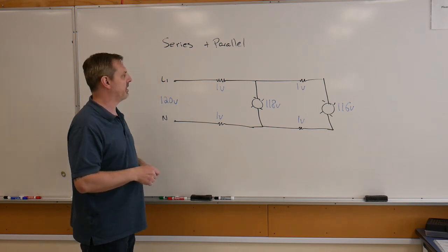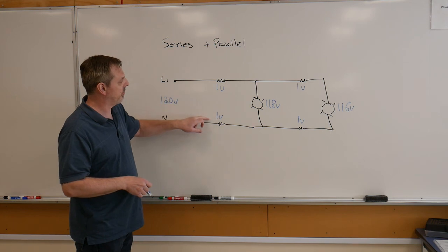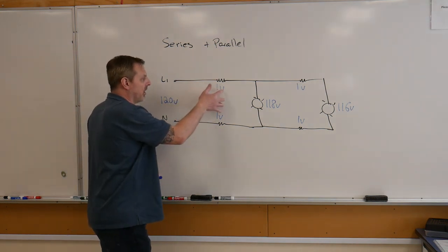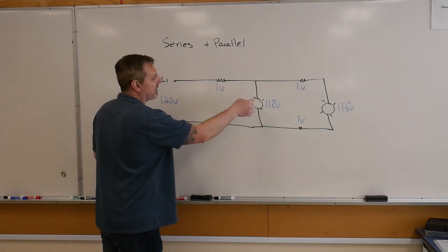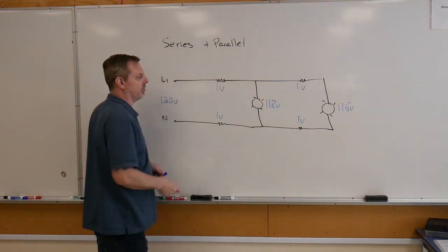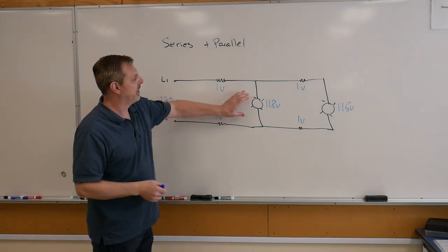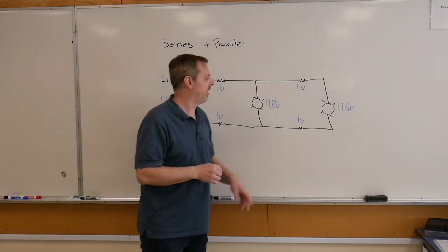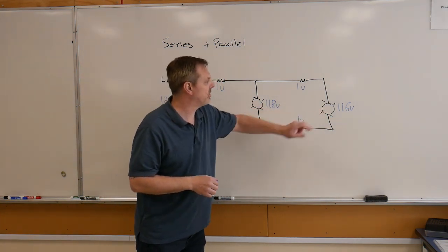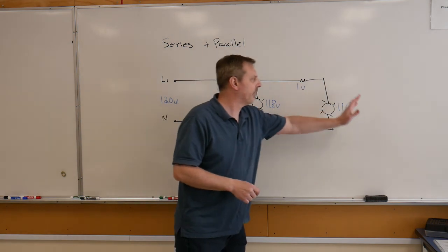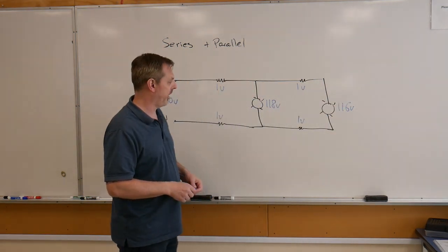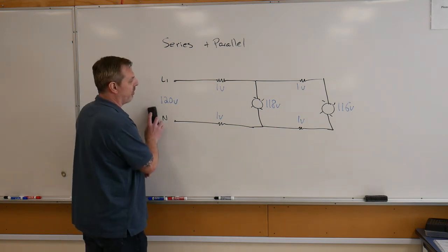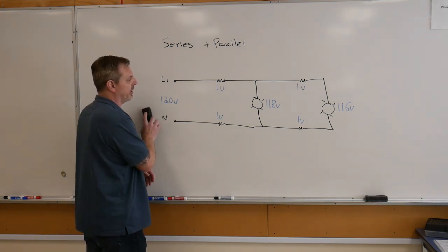It is also another reason why we try to mitigate the amount of resistance on the line conductors, to ensure that we get as little voltage drop as possible, maximizing the voltage output at our loads and minimizing the inefficiencies that could potentially take place further down the line. I've only highlighted 2 lighting loads here, but it wouldn't be uncommon to keep going further and further from there. So, that's a basic combination circuit, or the reason for us to learn combination circuits.